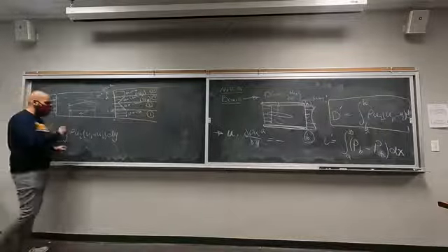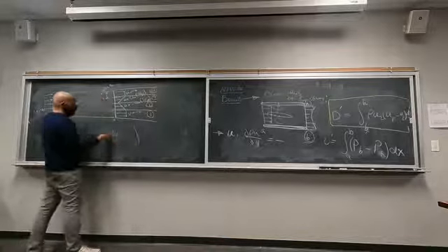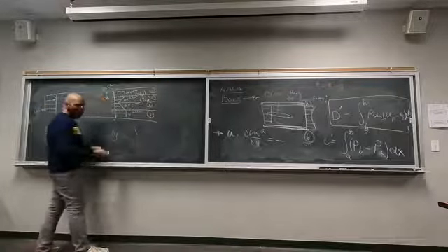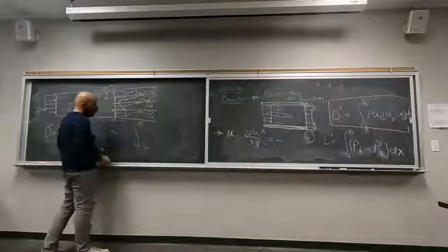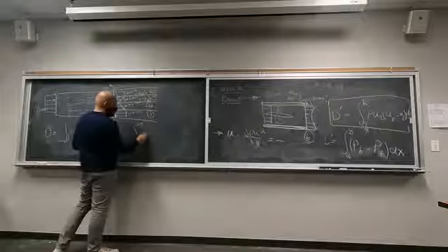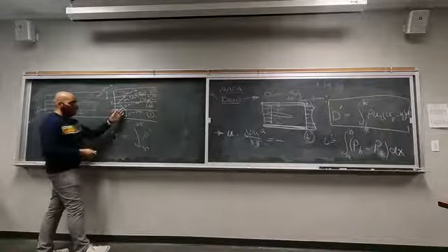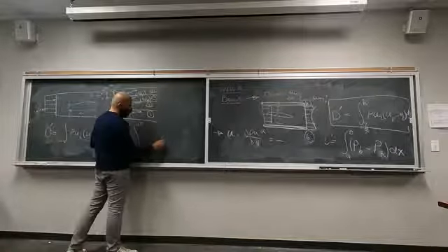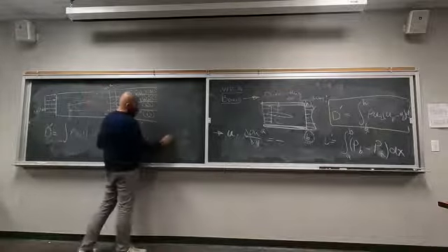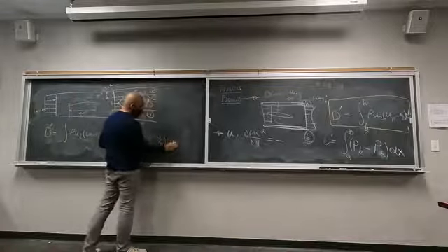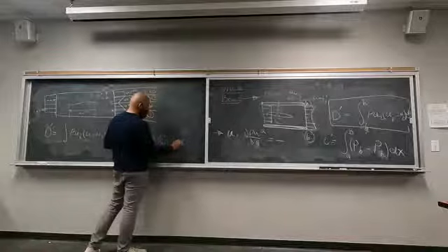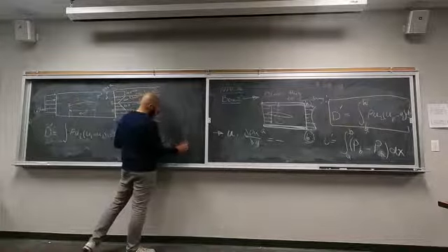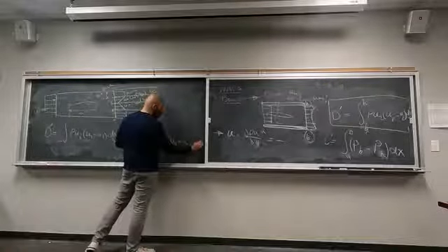Okay. What should we do for region 2? Which is going to be from 0.25 to 0.5, if we assume your chord length is 1. So the integral from 0.25 to 0.5. We're going to have rho multiplied by u2. What is u2? Negative u infinity y divided by h, multiplied by u1, which is u infinity, multiplied by, and it is minus a negative value, so it's going to be positive, u infinity y divided by h dy.